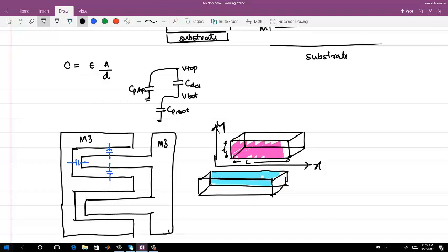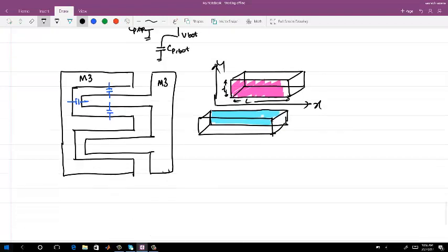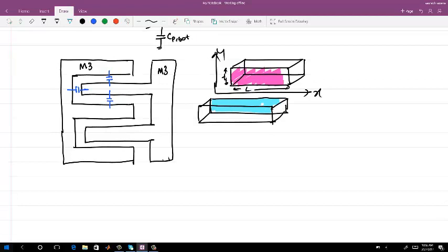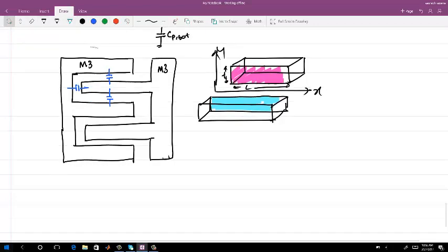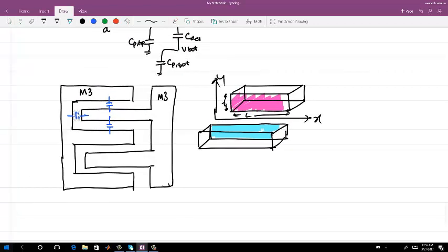So if the T reduces to 0, then you will not have any coupling capacitance between the two metal plates at the same level. So using this, you can realize the capacitance, which can be much denser also at the same level. What we can also do is, let's say this is M3, okay, so this you see as a fringe capacitance at the same level M3.